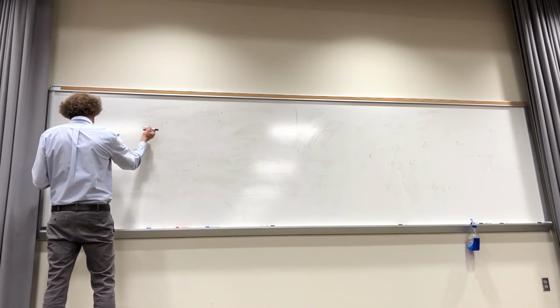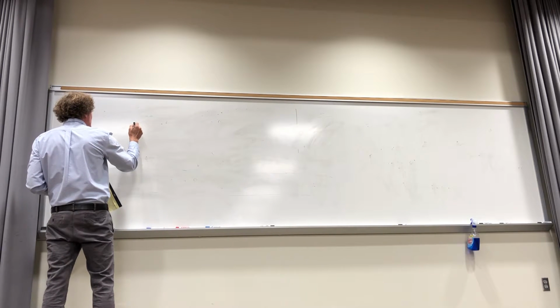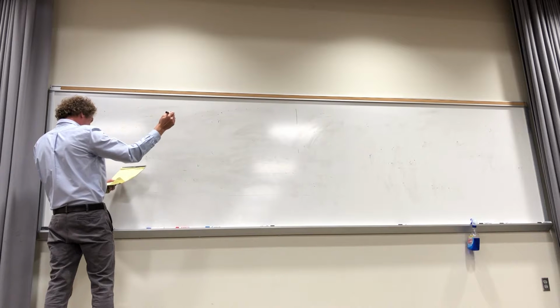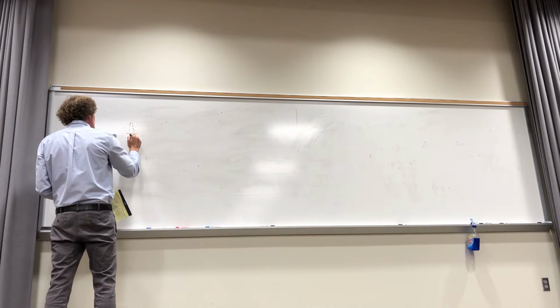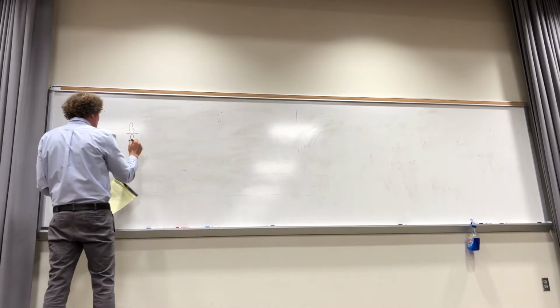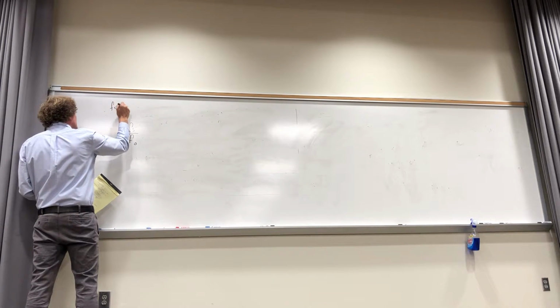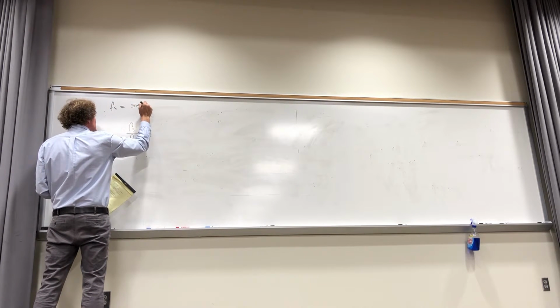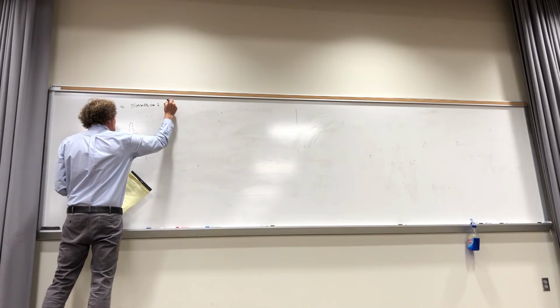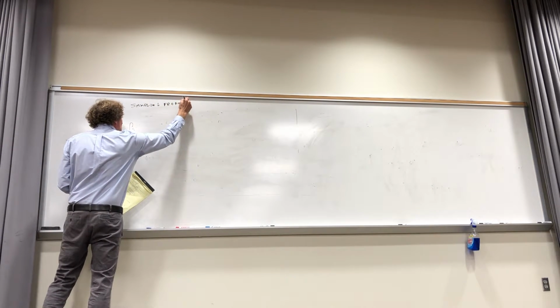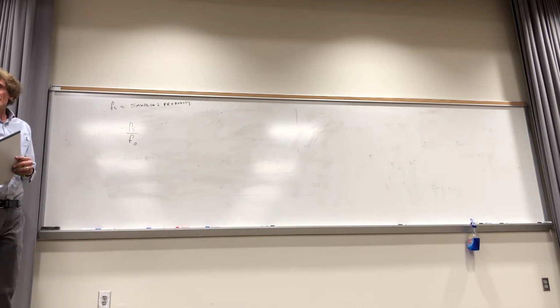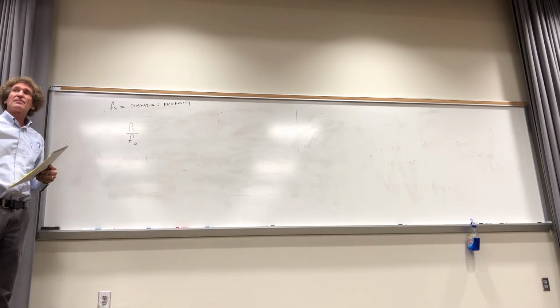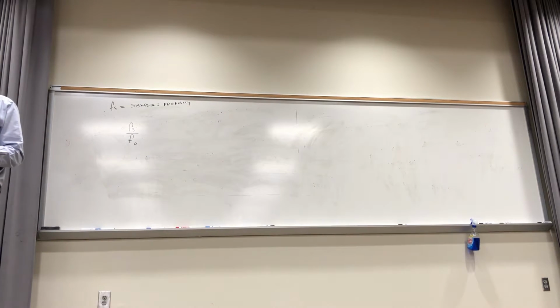The sampling frequency divided by the actual frequency you want to eliminate. Now, Fs for this one is going to be the sampling frequency. Sometimes you can't choose that. Sometimes it's given. For clocks, in a lot of standard chips that you buy, the sampling frequency is going to be the clock frequency, and it may not be tunable. However, if it's tunable, you're in luck. You can always do what I'm about to show you.